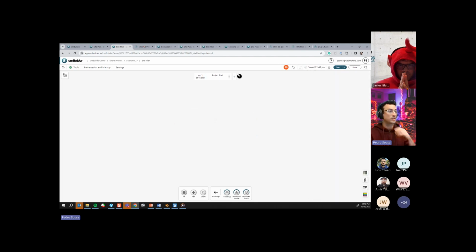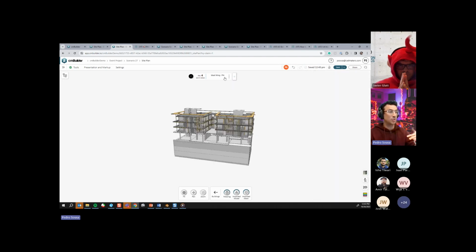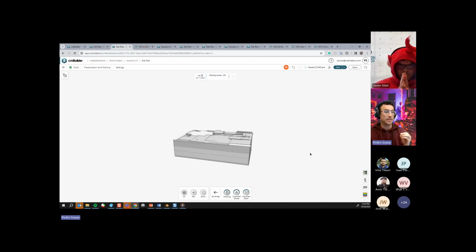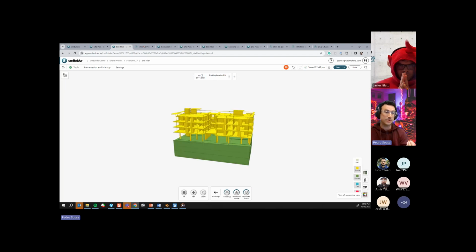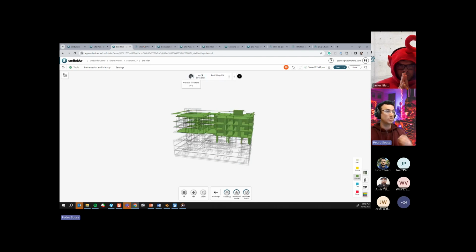So now I have milestones where these elements are going to show up, right? And the way for you to work with just those elements is to turn on your sequencing view, deactivate everything else, and keep only current. So now you have a view that shows those groupings.